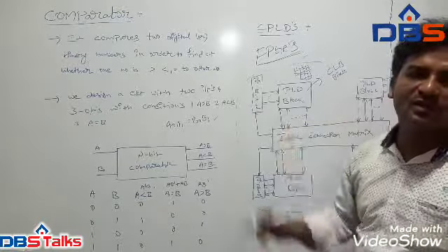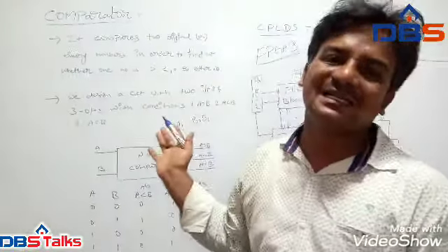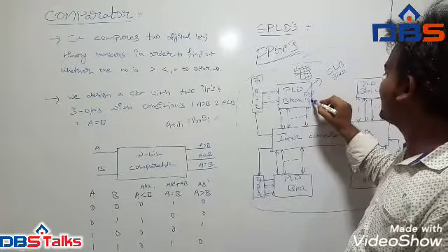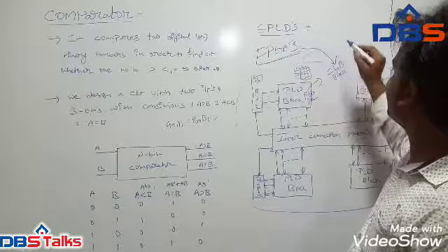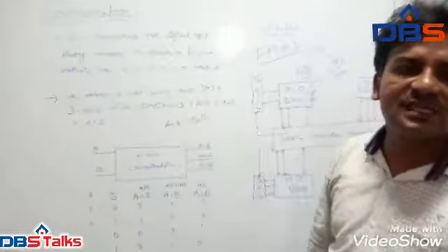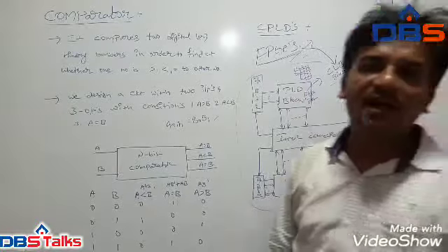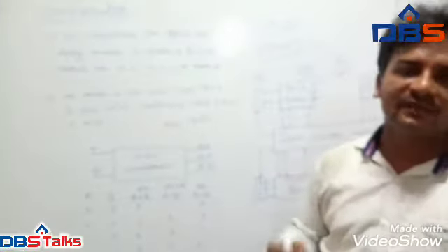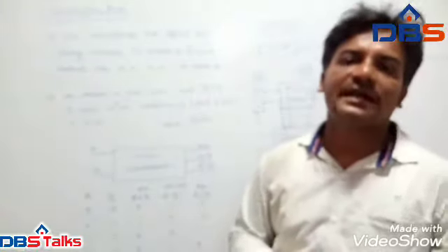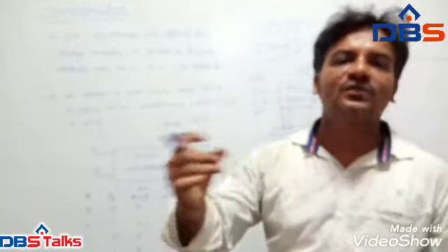So here we have to use programmable logic devices. Those may be constructed with the help of PLAs and PALs. But in FPGAs, the PLD blocks are mainly replaced by the configurable logic block. FPGA is also a programmable logic device, but it supports a large number of logic functions to implement a large functionality.